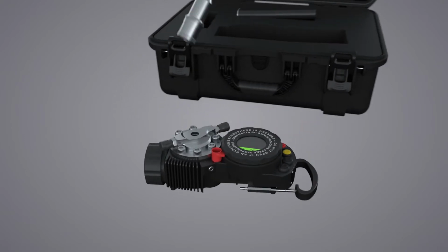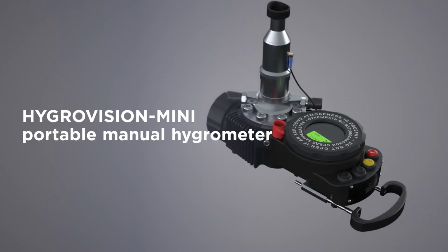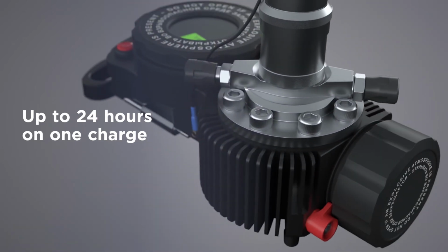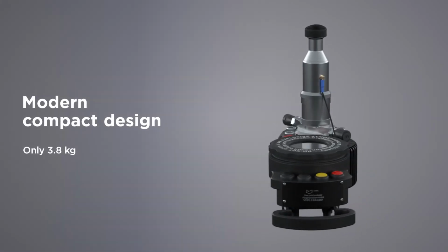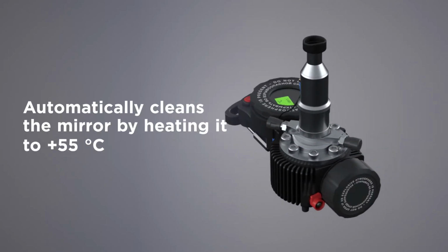The Hygrovision-mini portable hygrometer was developed for taking spot checks in the field and as a reference analyzer for checking the results reported by online automatic hygrometers. The Hygrovision-mini incorporates the condensation method of dew-point measurement. Equipped with a 40-power microscope, the Hygrovision-mini provides for both vertical and side lighting, making it easy to clearly distinguish between water and hydrocarbon condensates.